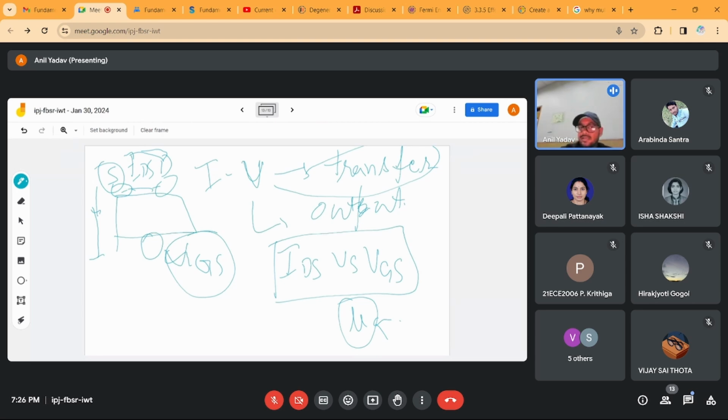These are known as field effect mobilities, a bit different from the electron and hole mobilities. In different devices, like LEDs and FETs, they will be different. They depend on the device, but we can estimate the material properties through this.